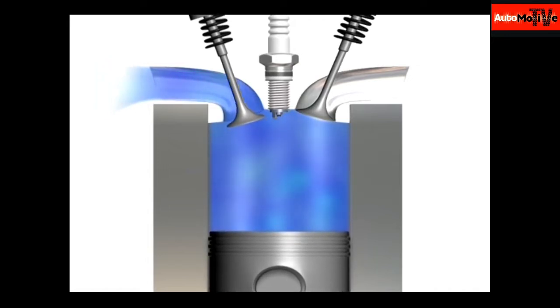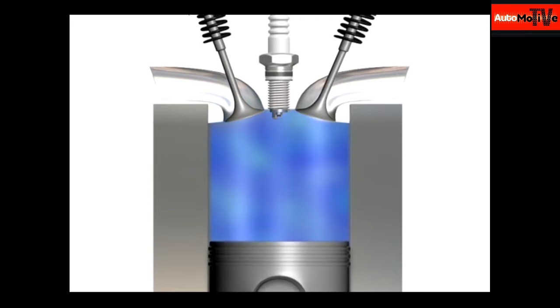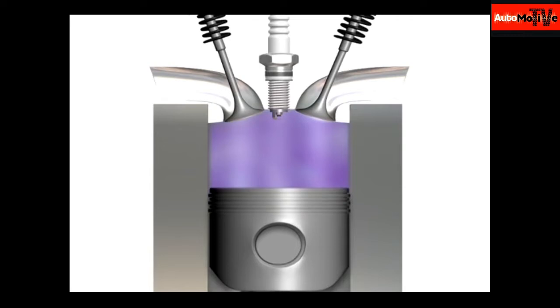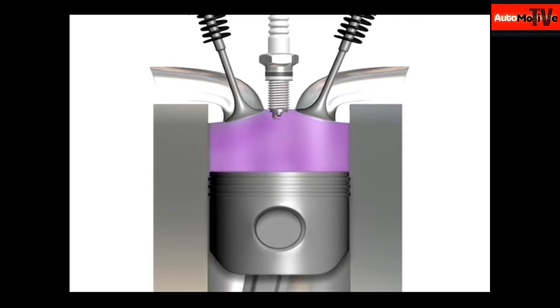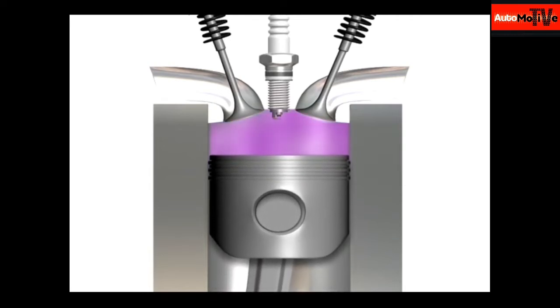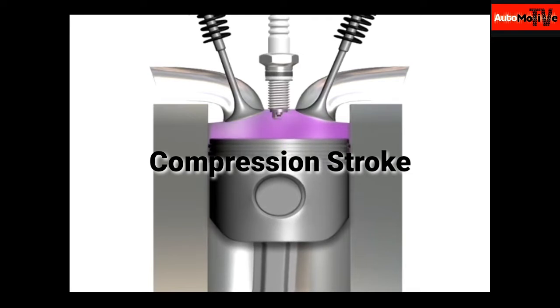Next, the intake valve closes, and the piston moves on an upward stroke that compresses the air-fuel mixture, which will make it combust with greater force than if it were uncompressed. This is called the compression stroke.